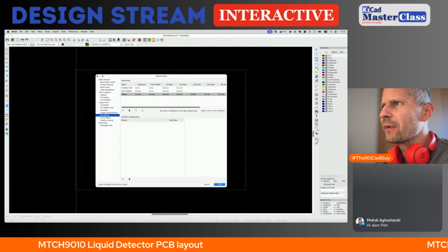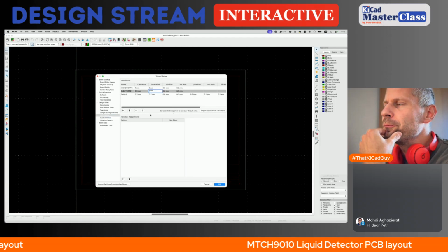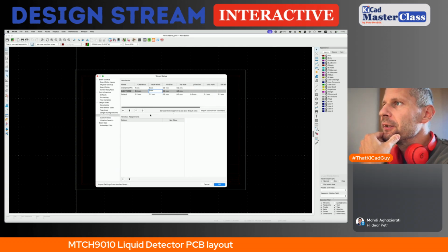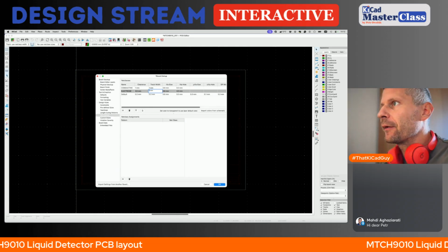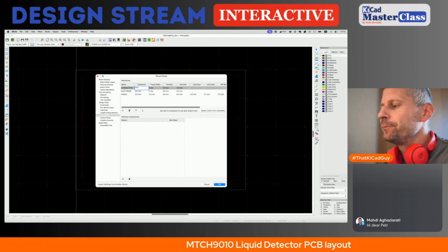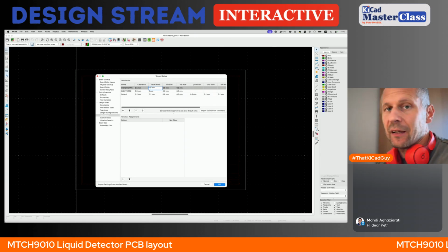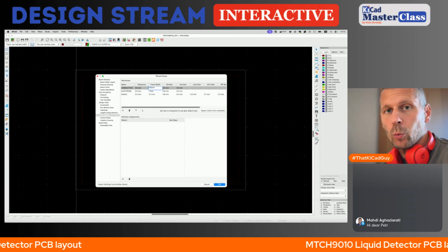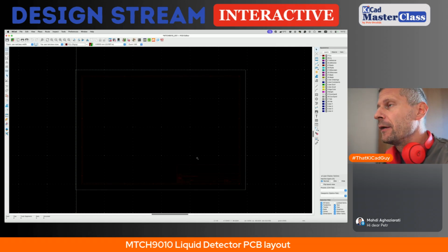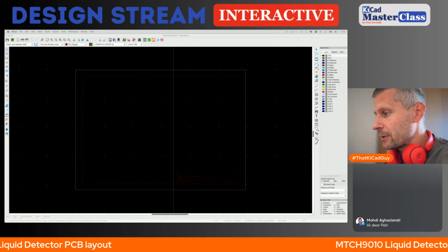So frankly, 2 mm seems too big, too wide. So I think 1 mm can be fine, and conductive 0.5, 0.5. I will set this, and if the PCB layout won't work well, we can change it anyway, anytime. Okay, so here are some comments, or at least one.